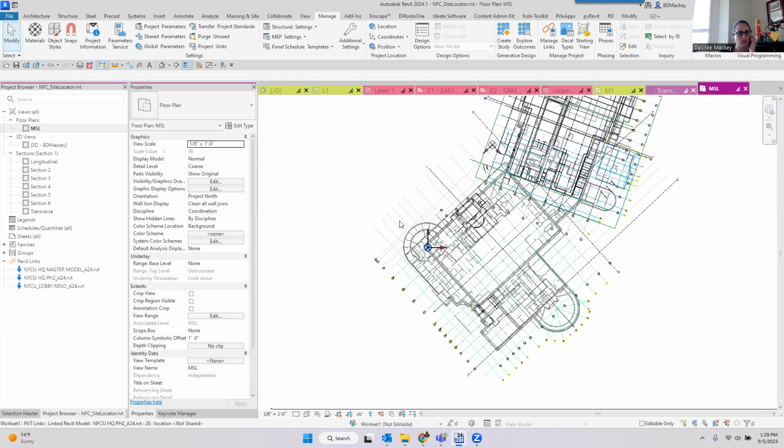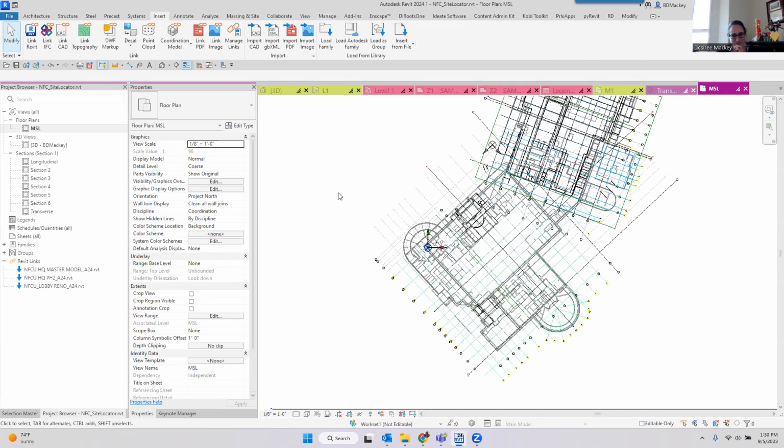And your next question is, what do you typically see a shared parameter file used for? Do you see it for materials, or what is it typically used for? I recently had to start a shared parameter file, even though I'm barely getting into project template and content creation, because for whatever reason, Autodesk doesn't think that EOR should be a project parameter. So that's the first one that I have in my file, but we both use a ton.